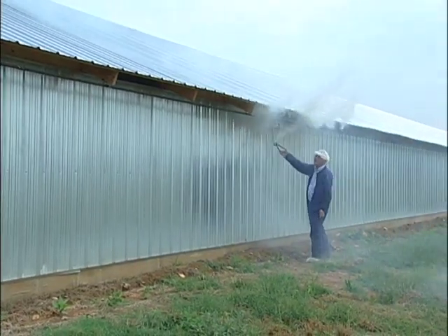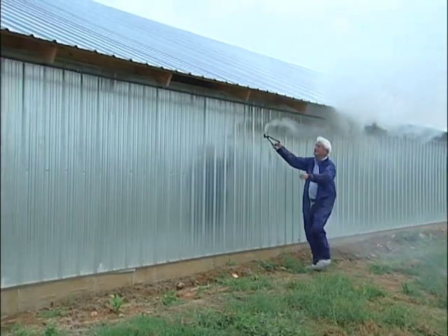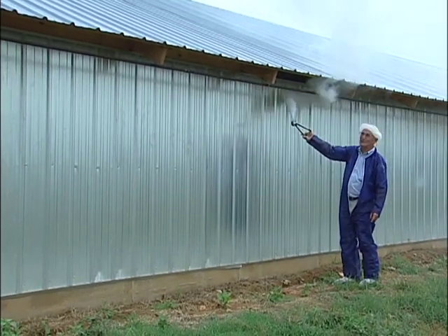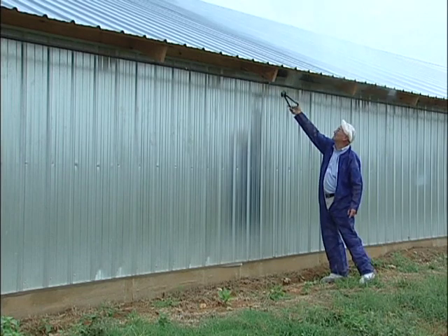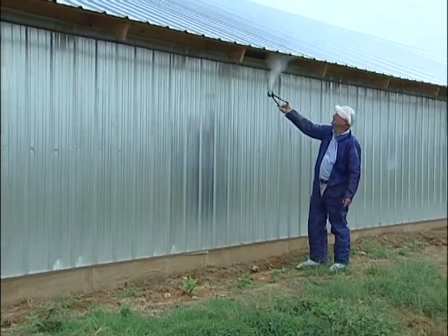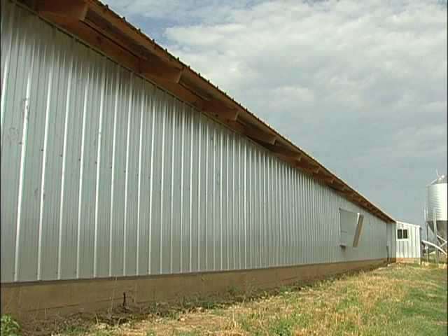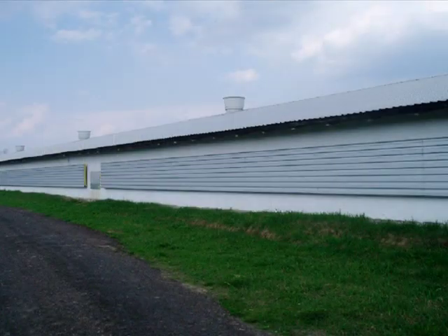Now we keep talking about wind protection on the outside of the house. We're outside here and the wind's blowing, and as you can see, we can't even make air go in the house because the wind either goes down the side of the house or goes over the top of the house. So we have to have all the wind protection that we can get. This is a wind protection on the outside of the minimum vent inlet or the transition inlet. That's extremely important when you're in high wind environments. And some of the houses that are built have wind protection that runs the full length on the outside of the house to prevent the wind from either side from affecting the condition inside the house.